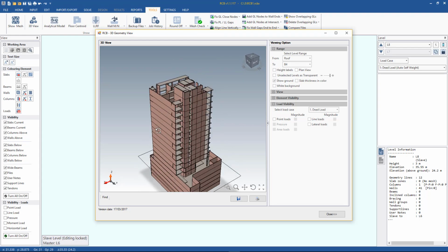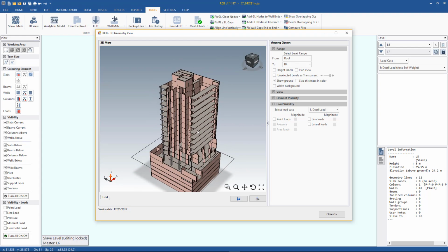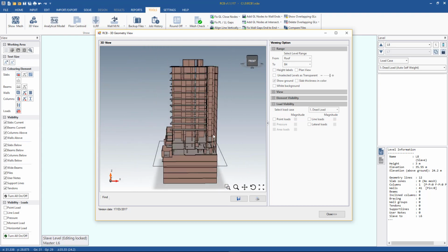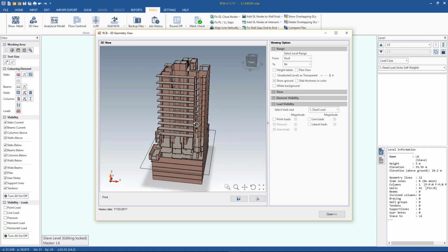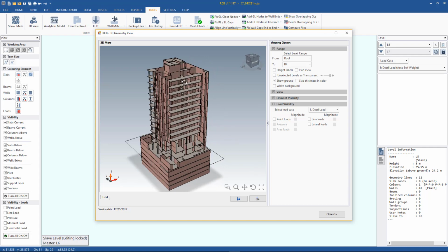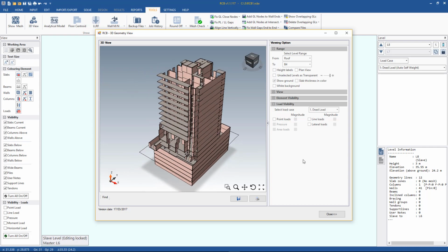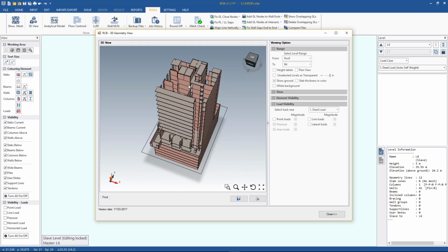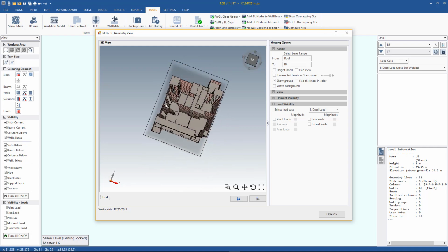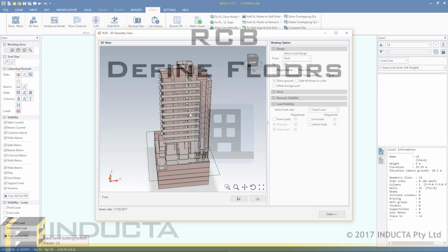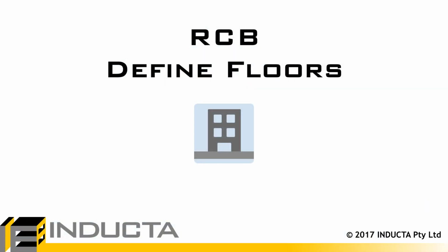But what we saw in this video was how quickly we could start importing all of the information from the CAD files into a model. So we made this 14-story building, including the lift overrun, in about 10-15 minutes. Now the next video will cover how to fix this issue where we aren't seeing the slab panel in the interior of the slab, and we will clean up the meshing errors in preparation for the first preliminary analysis.